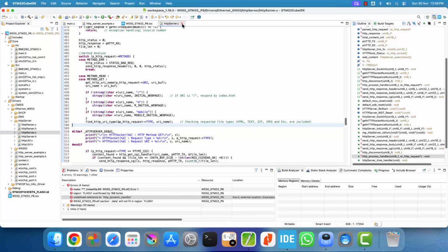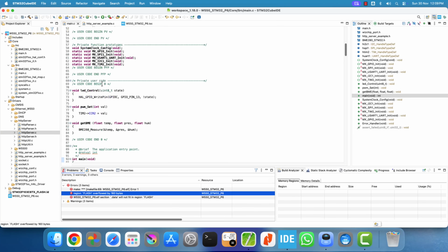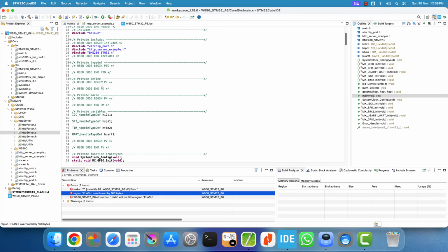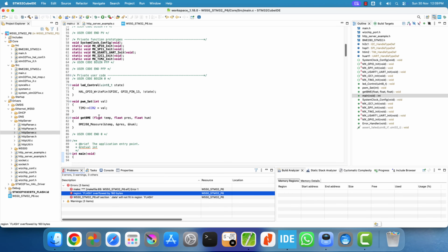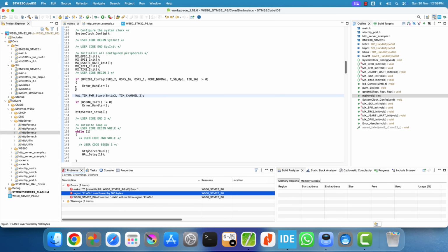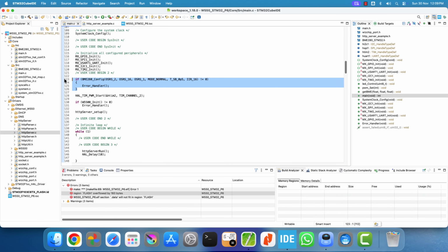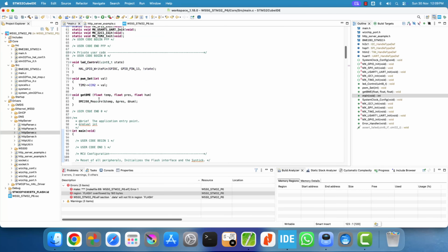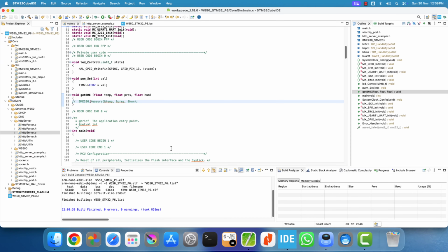We still have an error, and this time it is due to flash overflow. The blue pill does not have enough flash memory to hold the entire project with the BME280 code included. Just to test the server, I am going to exclude the BME280 related functions from the project for now. As you can see, the code builds correctly, and the flash usage is almost at its limit.